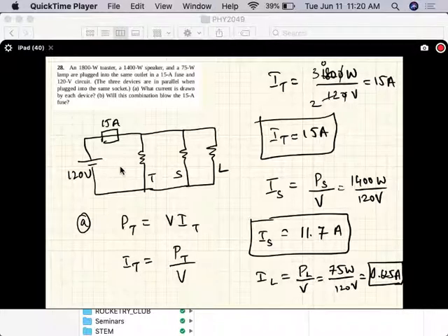Yeah, so each of those devices on its own is not blowing the fuse, and hopefully not all those devices together. So if this is a 15 amp fuse, and each device draws 1 amp, you can use 15 of those.